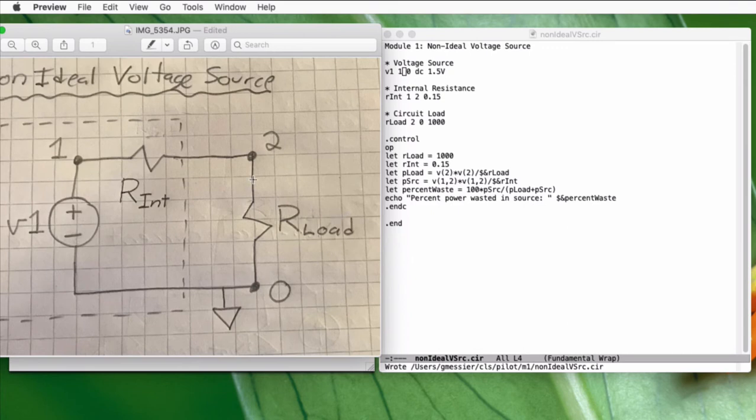And one thing you need to be aware of about Spice is that it is a nodal simulator. I'll talk more about that once we review nodal analysis in the next lecture module. But for now, it basically means that we have to label every node with a unique number. And just as a bit of a review, a node is anywhere the wires from multiple circuit elements join, right?